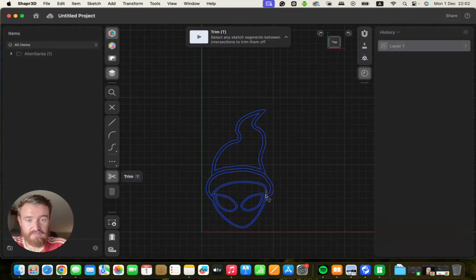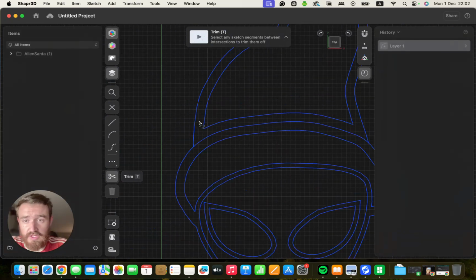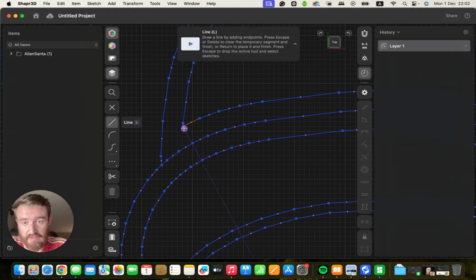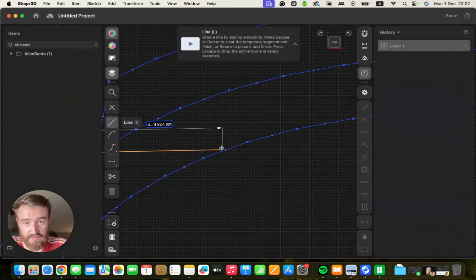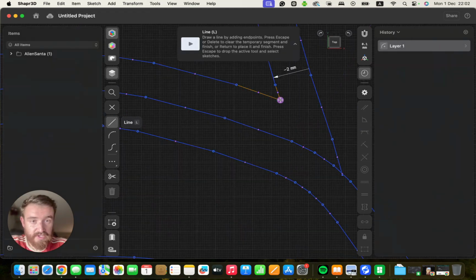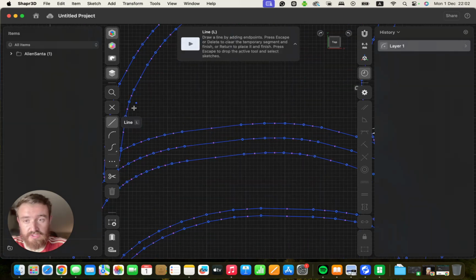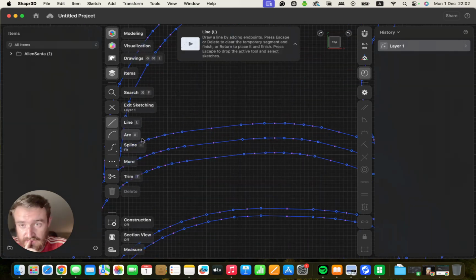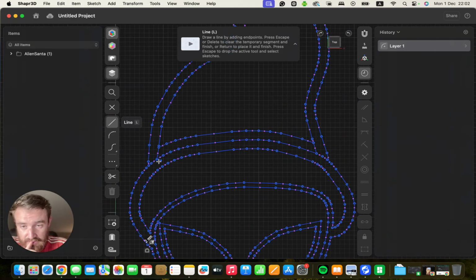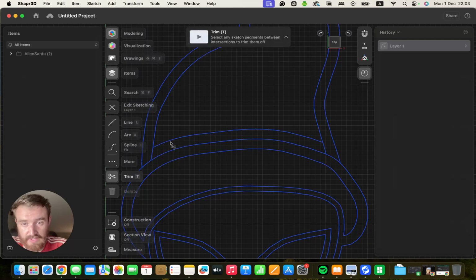All right, good. So it's looking good. Here, for example, we have a double wall. So what I'm going to do is grab my line and close it here, and do it again on this side, because if I have a double line, it's going to cut just too much. So I will leave it as it is here, and then I'll just trim all of this.